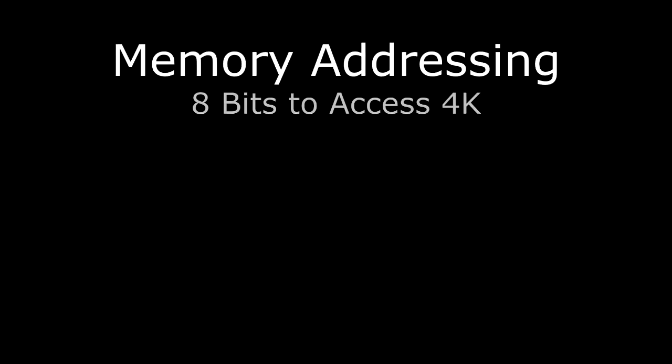Well, speaking of accessing memory locations, the first thing we have to figure out is how we're going to do that with this new machine, which has 4K of memory. The original had just 256 words of memory, so we could directly address any memory location with just 8 bits. Since we're keeping the format of 4 bits of opcode and 8 bits of potential address, we're not able to access all 4K of the memory in the new machine. So there are a couple of things we could do here.